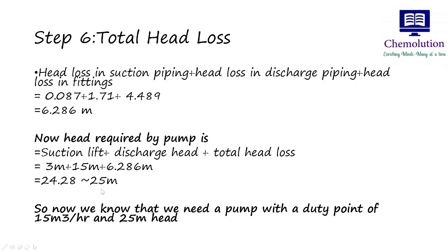So the head required for the pump to do this duty of delivering 15 meter cube per hour flow rate is 25 meter. So we need a pump with a duty point of 15 meter cube per hour and 25 meter head. So we have reached the point wherein we know that the duty point of the pump should be this much.